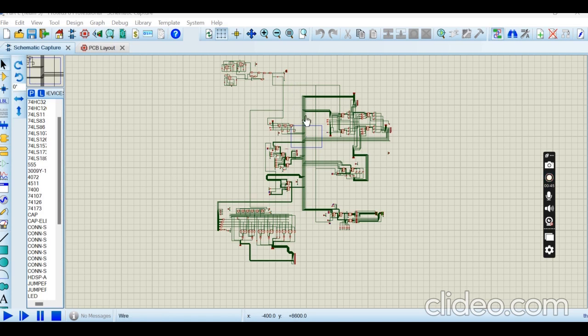First of all, we have some specifications in this design. One, we use a single 6-bit bus for both the address and the data transfer. We use an 8 by 6-bit RAM, which is random access memory, for storing the program and data.